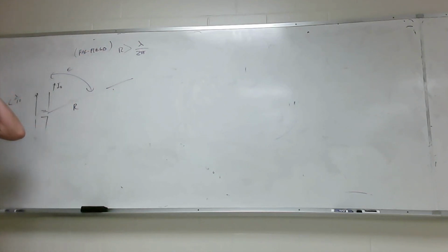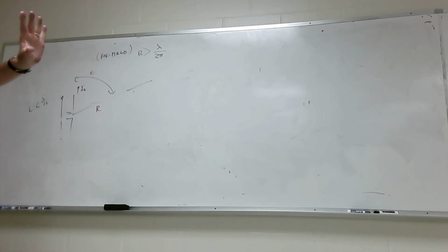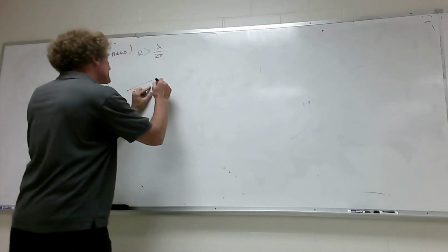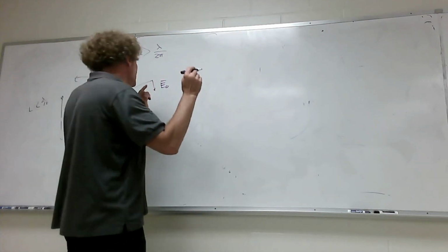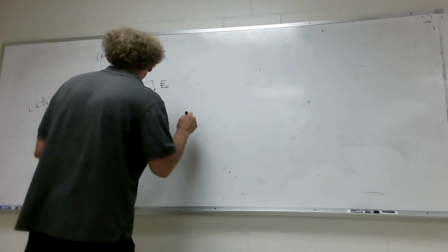I know you haven't had a lot of exposure to far field, but it becomes a very important concept. We're in the far field, the electric fields at that point and the magnetic fields are radiating. They're not energy you can get back. That's basically the demarcation. If you're at this point, you're going to get an E field. This you write down, it's in the book. You're going to get an E field from this constant current short dipole.